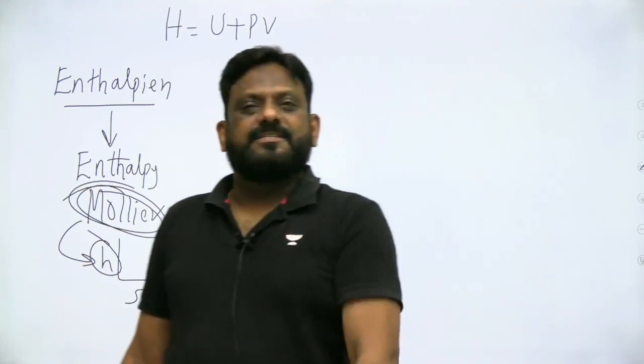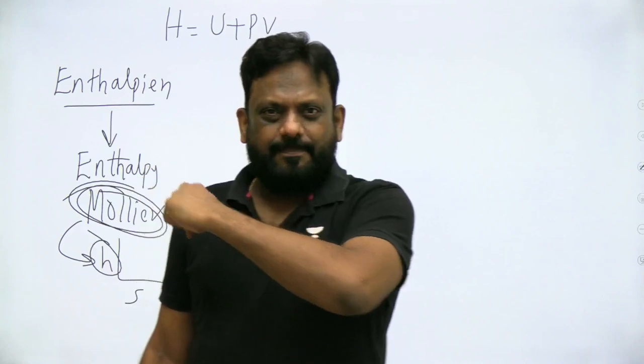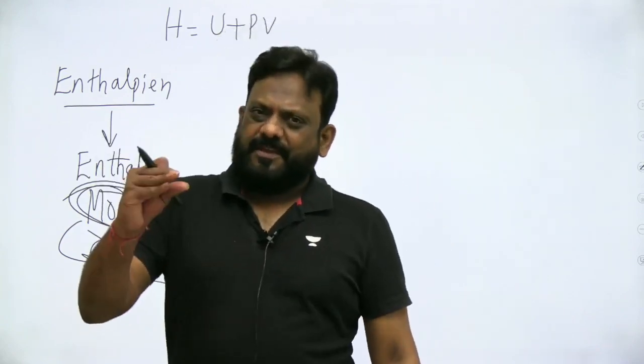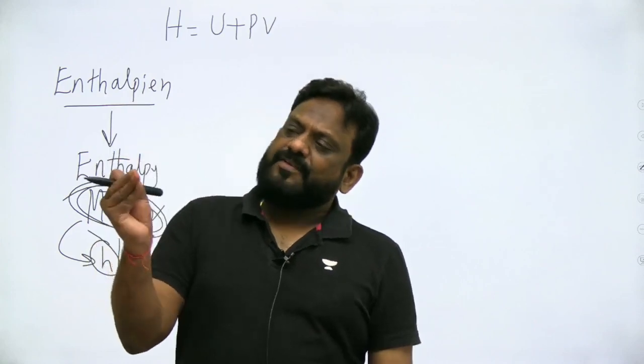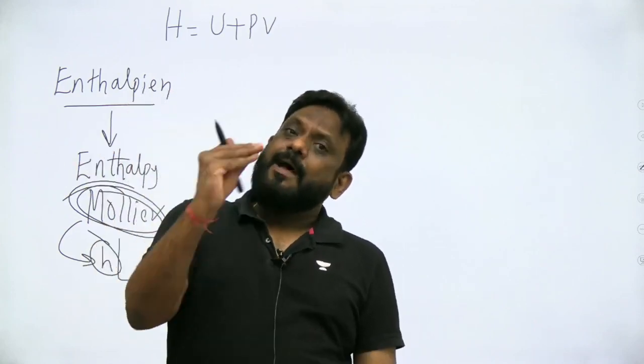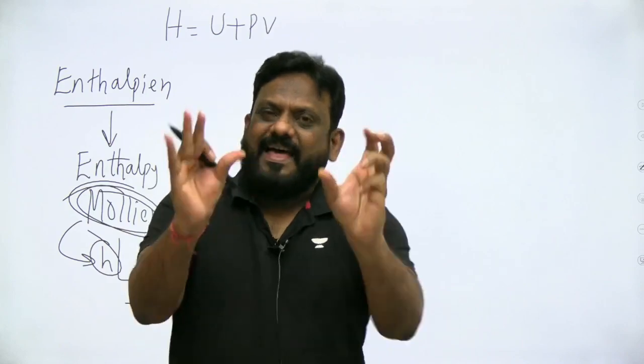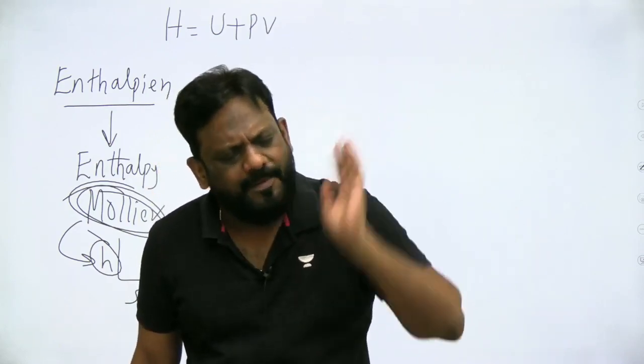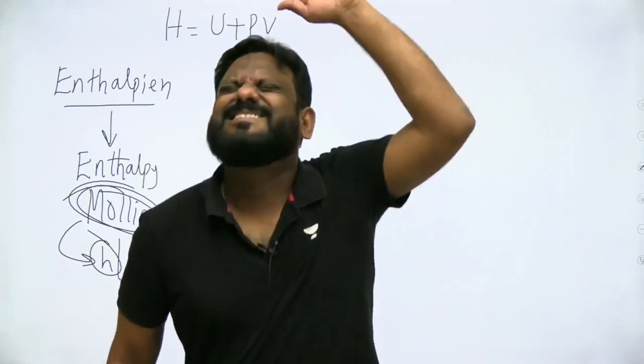Now let us take a closed system and see the beauty of enthalpy in a closed system, because already in an open system we have seen U plus PV: flow work, the work used in causing the fluid element to enter, plus internal energy. That component is enthalpy for an open system. So now I'm not saying that it is defined only for an open system. No. It is a general term.